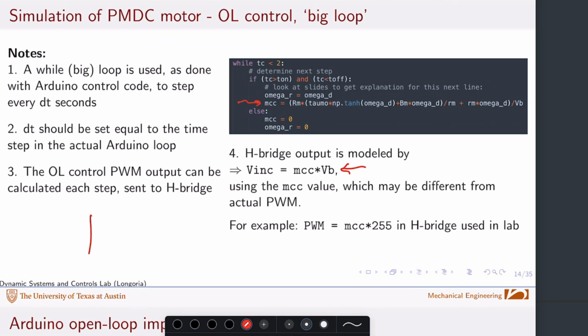And that's using a really simple model of an H-bridge that says if I have batteries here, and I'll show this some more later, and I give it a pulse width modulation input, it sets the average voltage here. That's a rough, nice, simple little model of an H-bridge that you can use in these simulations, and you can play around with that.